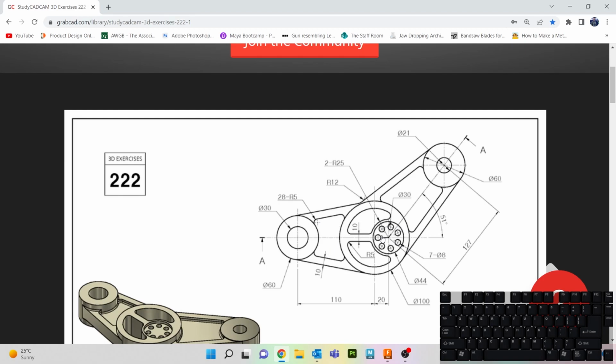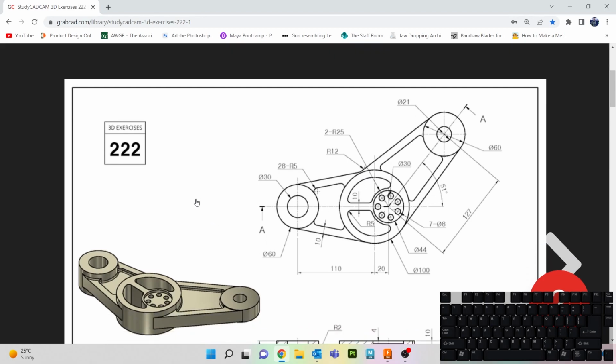It was just a circular pattern, diameter of 8, and so on. We knew this internal circle here. The only one we didn't know was this external circle here. And even looking now, it might well be that after I've recorded this and posted it, I go, oh yeah, it was here. The only thing I did was, because it looked the same as the distance from there to there, which is 10 mil, we did an offset from that circle of 10 mil. That's the only one we couldn't quite get.